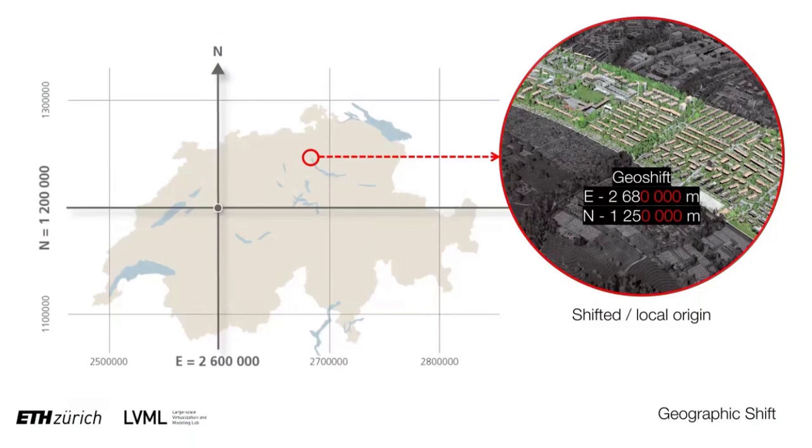And again, the geoshift is just a temporary measure. As soon as you save again the data set, it will add again the shift. What I suggest is always to use the same shift, because then if you combine different elements, they all have the same geoshift. And the best way to do that is to round off the data set with 4 zeros.